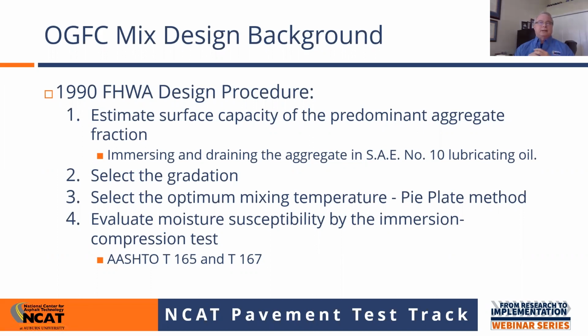They determine the surface capacity of the aggregate by soaking it in lubricating oil, and they take some measurements. They select a gradation, select an optimum mixing temperature. They use the pie plate method, which is still used by several states today. Pie plate would set the mixing temperature. And then they would evaluate the moisture susceptibility by slightly different tests than what we do today. So the world was a little bit different back then.